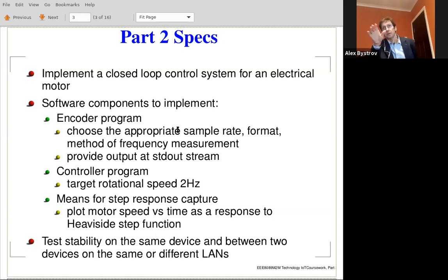On the other hand, you can take this sample rate like half an hour, and you will accumulate plenty of samples and have very accurate measurements, but the lag will be huge, so it will probably not be useful in controlling the motor. So somewhere in between there should be the optimal value for our design. I'm using 20 milliseconds in my sample examples. Well, I thought that was reasonable.